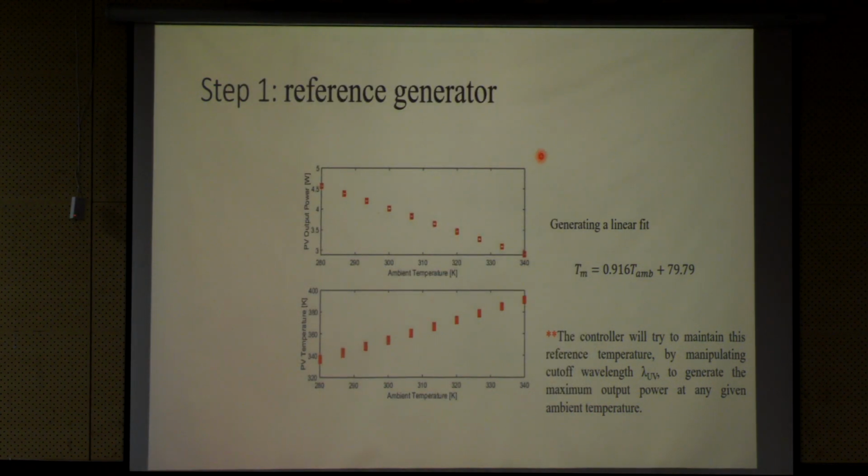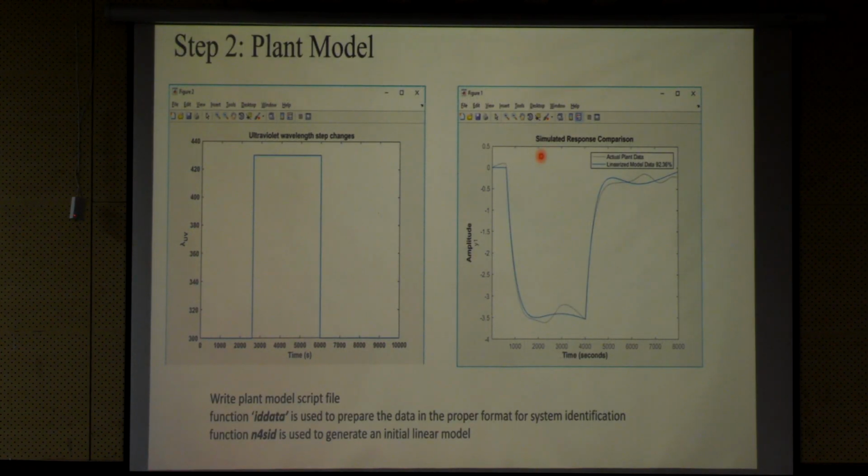Okay. Now after the plant model is ready, what will we do next? We have the actual plant data, we know how it is. We are trying to fit the linearized plant model that we have built. From there we are linearizing and trying to find out the best fit. So if you see in this graph, I will run it in MATLAB also, or if not, I will provide you the code also. You can see step by step how it is.